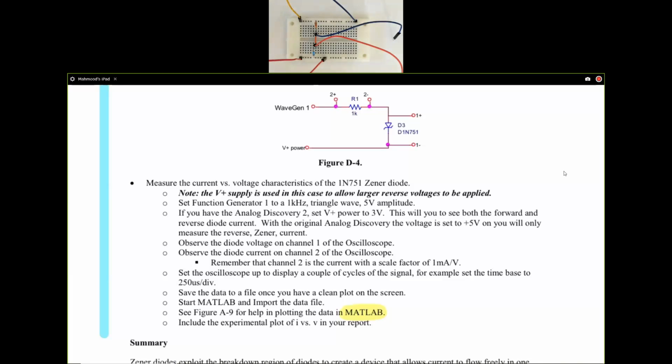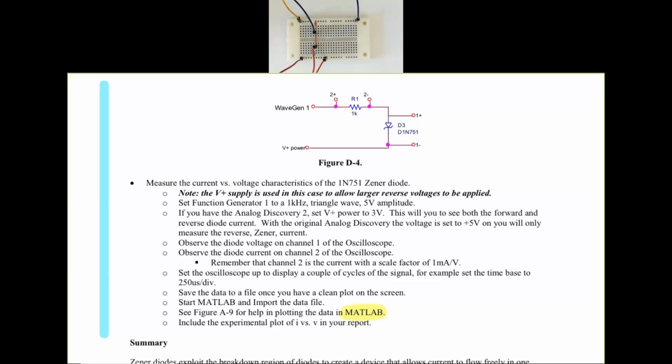So I'm going to make the connections here to my Analog Discovery pinouts and start WaveForms. For blue, this guy is supposed to be the negative, that's the blue stripe, and I have blue on blue. Okay, so that completes my connections to Analog Discovery. At this point, I'm going to start WaveForms.